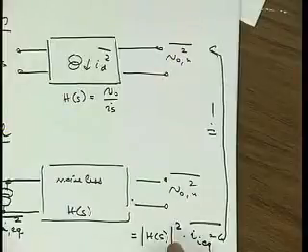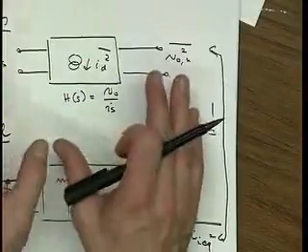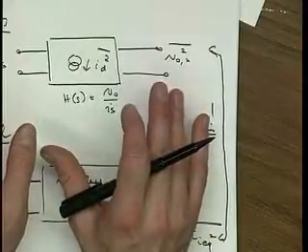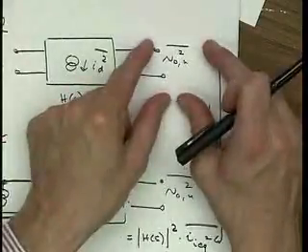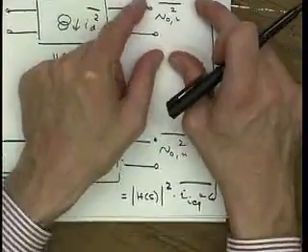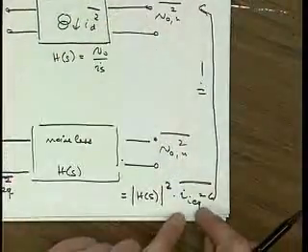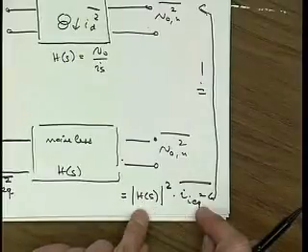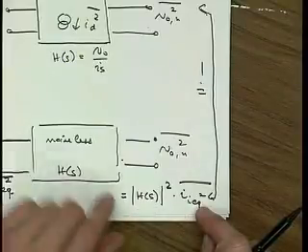And now it's a trivial thing. When I have a circuit, much like the common source amplifier in our previous example, I calculate the total noise at the output. And then based on that, it's a snap to calculate the input referred equivalent noise source, simply by dividing by the transfer function of the circuit.